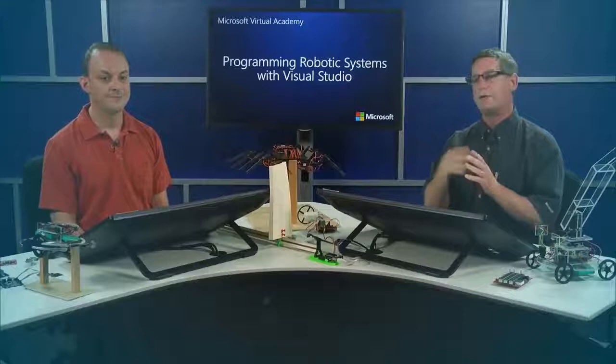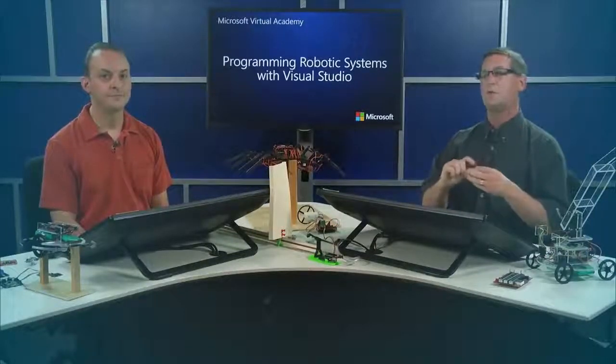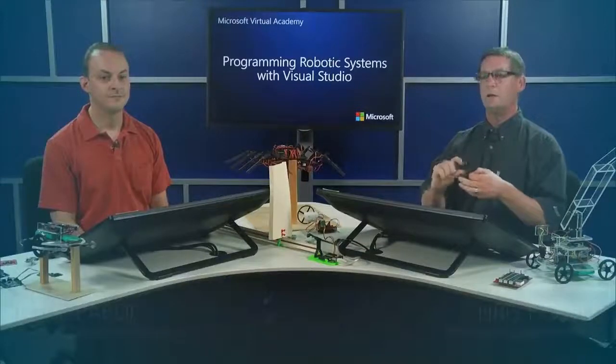Positioning the sensor, the rangefinder sensors, right? We could have used it, and it's nice. It's very repeatable, and you can get a pretty big, strong stepper motor. You can get, Paul, for the 3D printers. That's what I was just going to say, the 3D printer that I saw in your office, you have a couple of those on the 3D printers that use the same. So it's a good motor to use for the application that you need. Very precise, right? Like in 3D printing, you want to be able to move very precisely, very incrementally, and very repeatable, reliable, right? Yep. So a stepper motor is good for that.